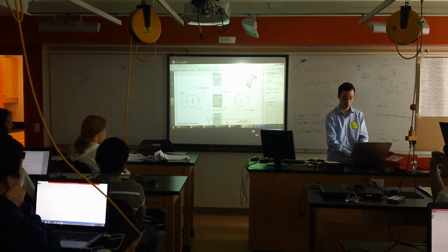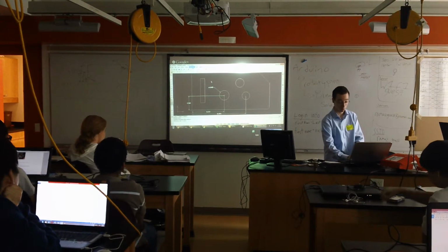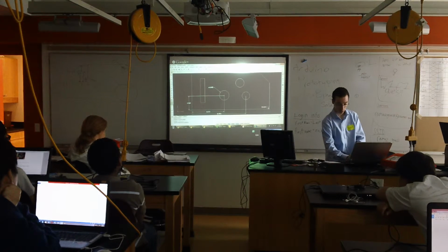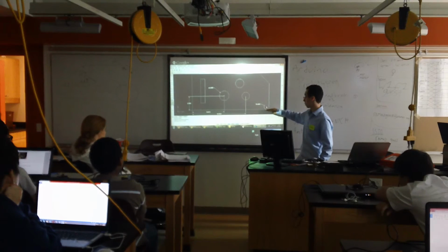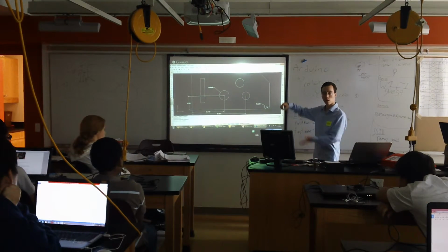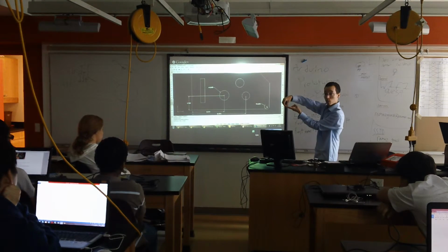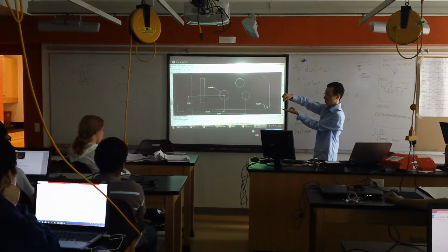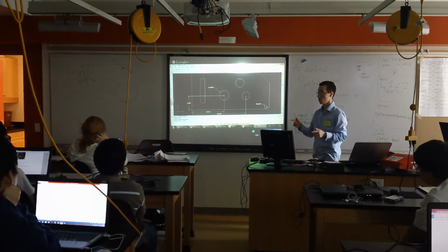In this case, we have part of a circle right there. So I will just go again, dimension, radius here. And as long as I specify how far this is away from here, we're assuming that this circle is tangent. We get what I mean by that, right? The circle just barely touches that line, and we cut the line off at that point. So if I specify how far out this is, I know where this point is on the circle, I know where the center is, I know its radius, I know everything I need to know about it. That answers your question? Yeah.